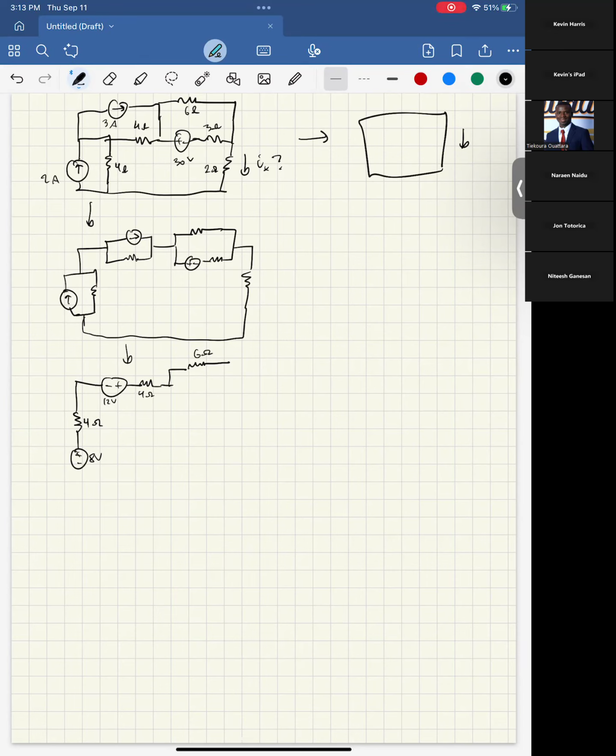However, this bottom part here will split into 2 branches because it's becoming parallel. So we have the resistor, which is 3 ohms, and we have the current source now, which is pointed to the left. And remember, I equals V over R. So this will be 30 volts over 3 ohms, which will give us 10 amps. Then that goes through this 2 ohm resistor, and we're still not done because we still have a branch here, but this can be recombined pretty straightforwardly, right?